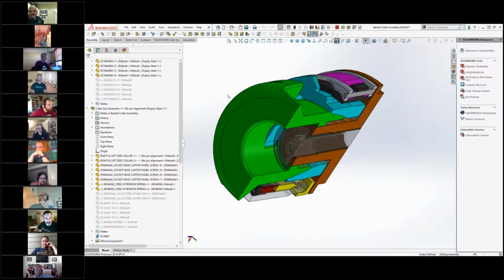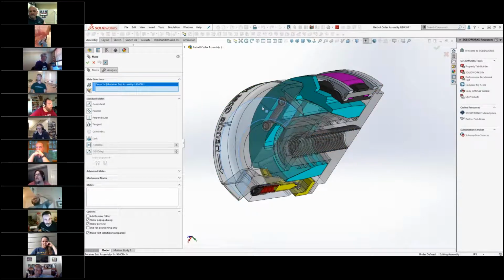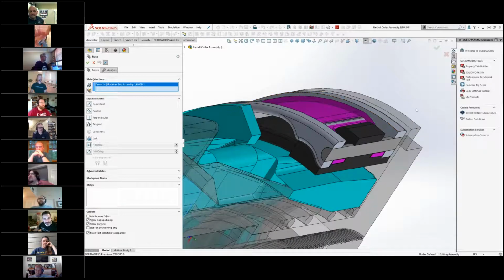Let me go back into the mate command. So I'm in the mate command. Come on, there we go. So click one face, just regular click. Yep. And now hover your cursor over a different face and hit Alt once. Yeah, there it is. Nice. It's basically a delete face. It's not the surface body. It's like a select other shortcut. But only in mates, it'll do it to any surface. Look at, I'm hovering over all these surfaces. And you can keep going in and in and in.